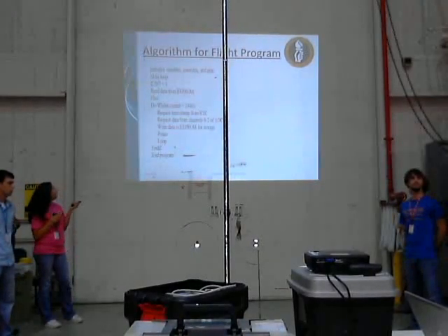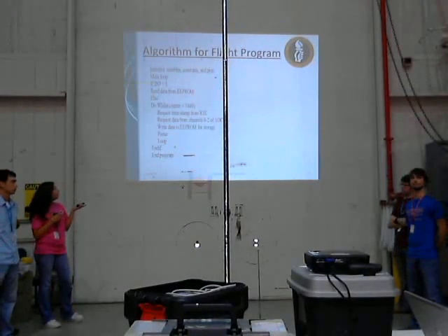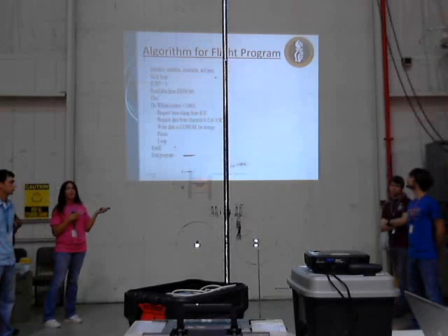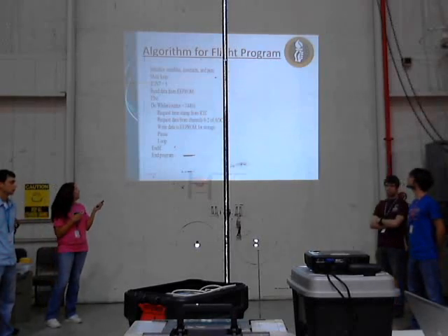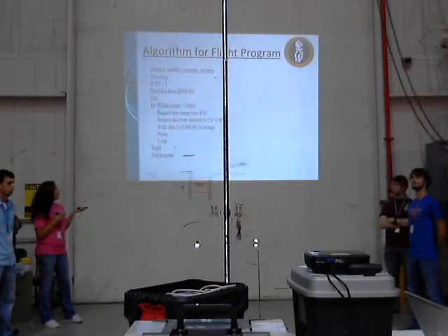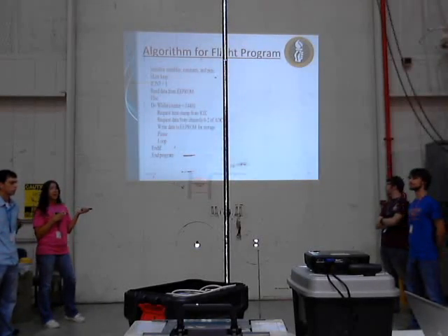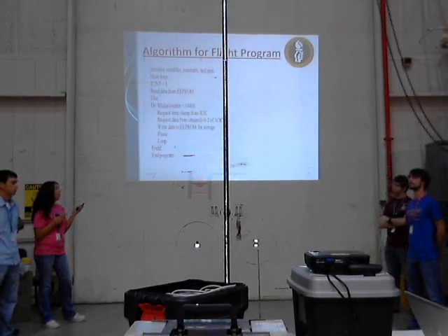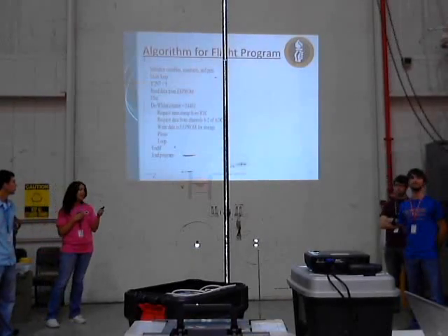During the write mode, we will be getting our time from the clock. We'll be getting the data from the channels 0 through 2 of our ADC, and we'll be writing each data to EEPROM on each iteration, and we will pause and wait for a 10-second loop.